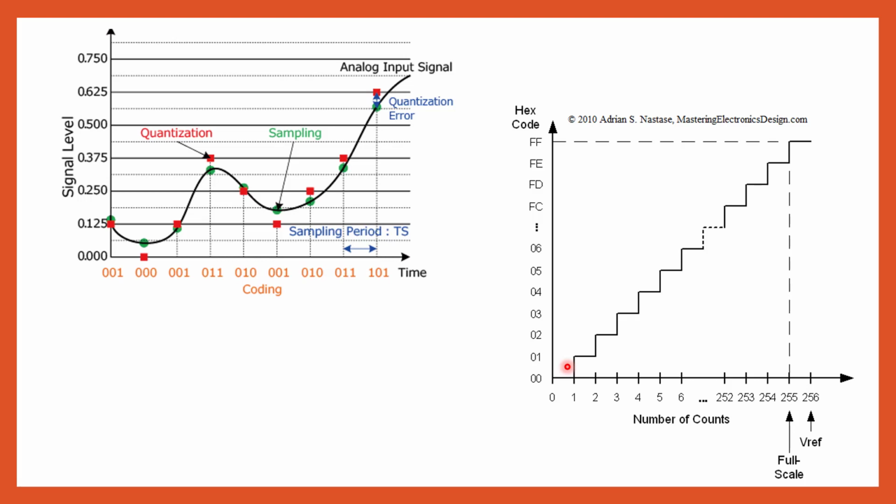And the smaller the steps I have, means that I took more samples. Because if I were just sampling here and here and here, each one of those samples takes a certain amount of memory. But if I'm increasing the rate that I'm taking measurements, each one of those measurements has to be recorded in memory. So I'm consuming more memory the higher my sample rate.